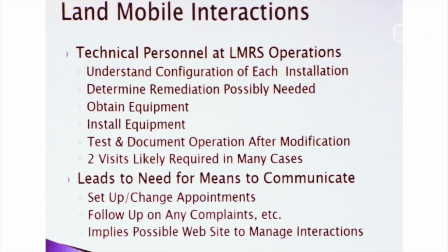In the case of that tower that I just showed you, there's somewhere between hundreds and thousands of land mobile operations within a reasonable distance of that tower. What is a reasonable distance? That's one of the things we have to determine. In any event, it implies that there's going to be a need for a long test period because somebody's going to have to be at each one of those sites to measure the 1 dB change in the noise floor, and the only way you're going to find that is turn the transmitter on and off.